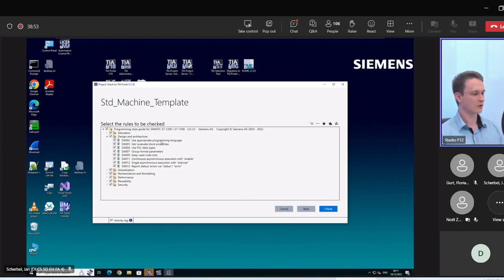And programming blocks which gather or collect content, maybe where we have to define a module with 4 drives, are mostly recommended to be programmed in a graphical language. Also, we recommend using the PLC data types, so we avoid structs and other custom large solutions, because when you use the data types, your program gets shrunk down and it is more performant.